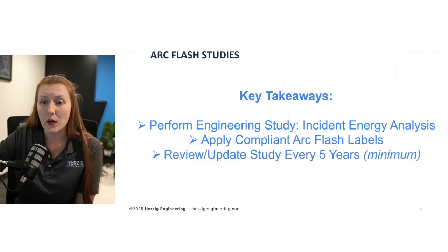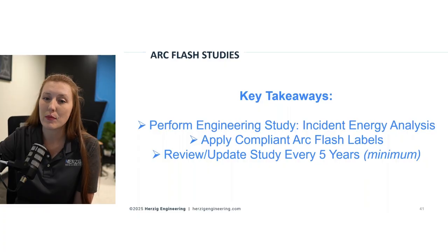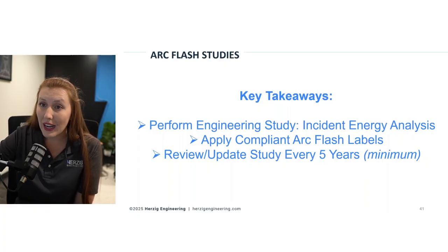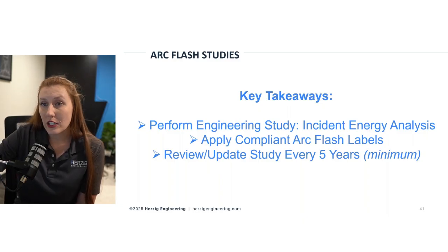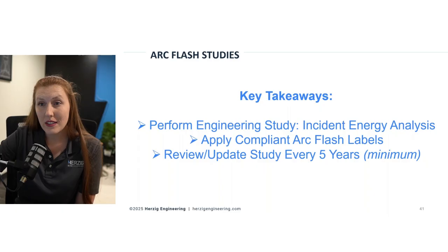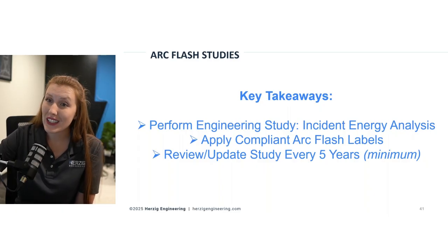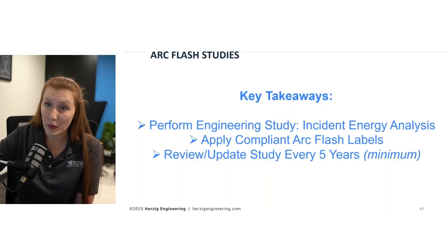So what are the key takeaways? Get an incident energy analysis performed. Get that engineering study performed. Make sure that they're applied and on the right pieces of equipment, and review and update your study every 5 years, or if something changes, because again, if the data doesn't match, that study result isn't going to help you.